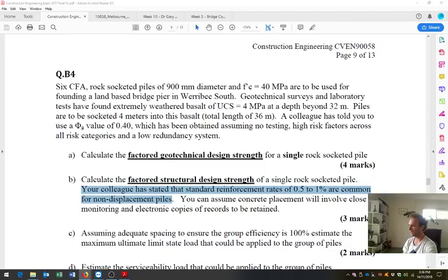Do we have a conservatively assumed? Look, I think most bored piles, if you're boring a pile, you're going to fully reinforce it. You need a lot more capacity, so bored pile, fully reinforced, unless stated otherwise. Thanks for the session, Norris B. I hope it's been helpful.